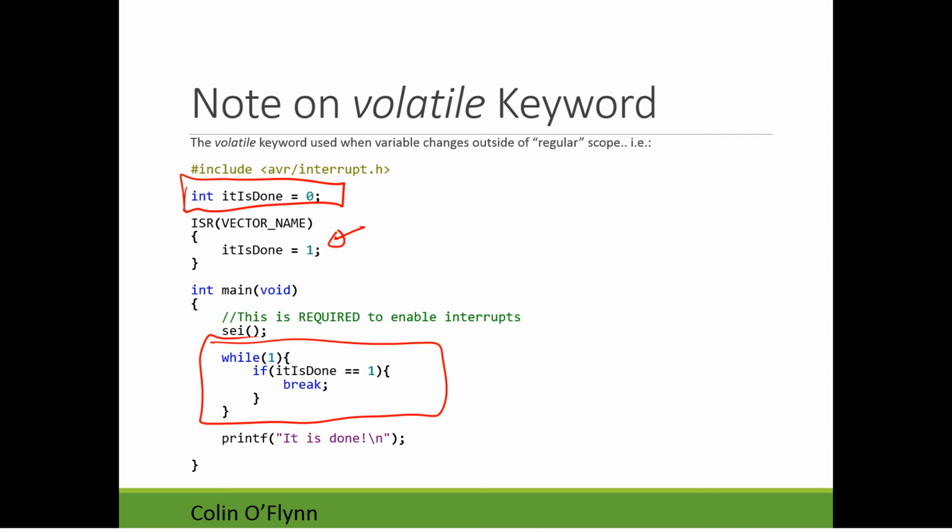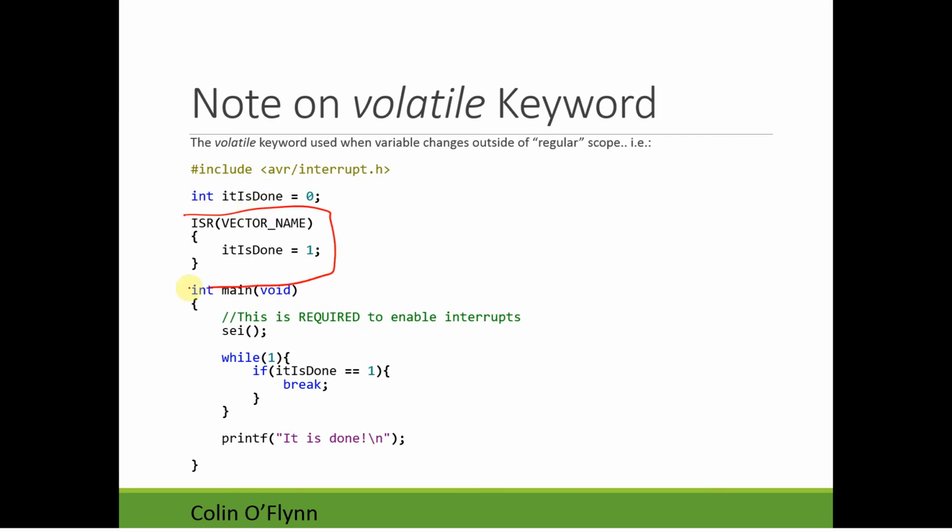The compiler will look at this code, and the problem is it has no idea when this interrupt is called, so it just says, well, maybe it's never called. That's what it assumes, because there's nowhere that you explicitly jump to it from within your code. It just sees, okay, you run this weird macro, SEI, and then there's a while loop. And that while loop will never exit in its mind because it is done was set to 0, and there's no way to set it to 1.